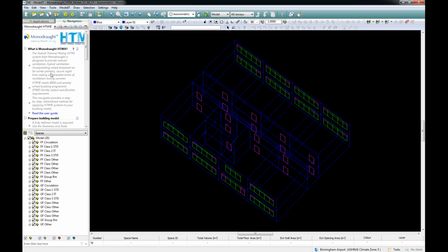This is also designed to meet all the acoustic requirements of BB93 for the UK, where the noise levels can't go above 35 dB. So we've designed the system so it can maximise the ventilation performance through the low energy fan while still staying within the required noise levels.